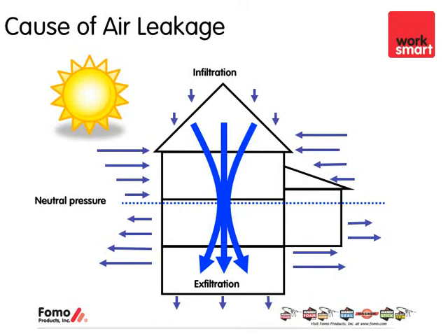The warm air is finding its way through the attic, through the small penetrations in the attic, into your second floor. And then that is now exfiltrating out through the bottom of the house. So what's happening is that warm air is pushing the cold air down into the basement and it's escaping out. That's why your basement feels colder and your second floor feels warmer. So this would actually be a stack effect, but in a reverse format.